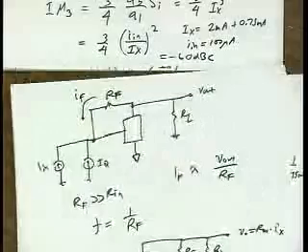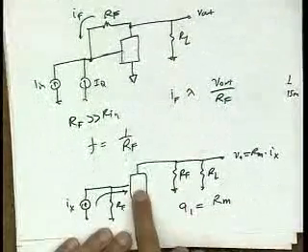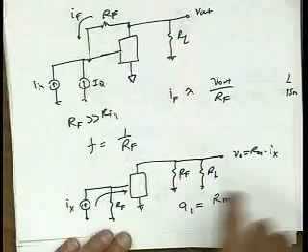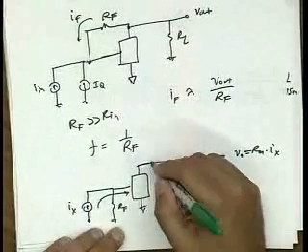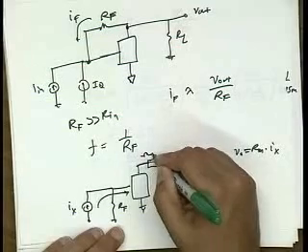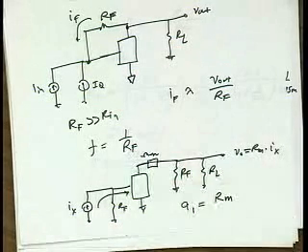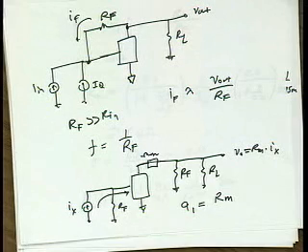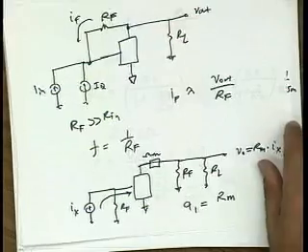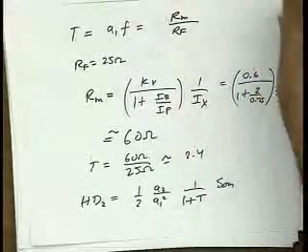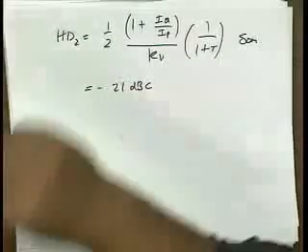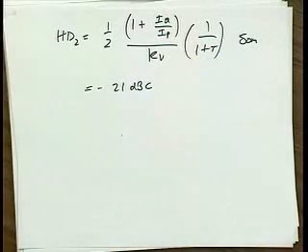As far as the output voltage goes, the output voltage has a voltage divider effect because there's an inductor L in series here. And so we've neglected that. But if you want to do a more careful calculation, you could easily include that too. Could we have made an expansion around IQ equals 2 milliamps? Then we would have gotten A1, A2, and A3. That's what we did for part C. It doesn't work for part D.